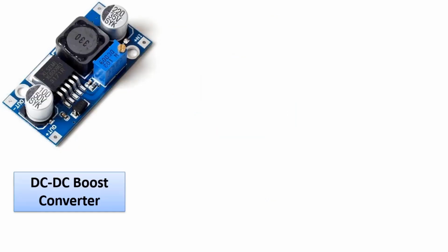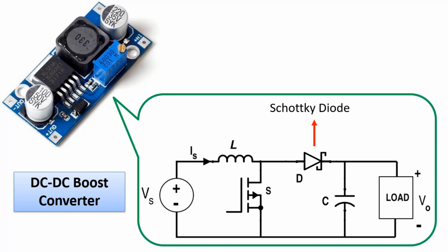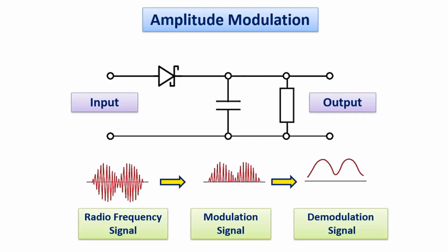Here you see a DC to DC boost converter. The circuit diagram is basically like this. The step-up process is based on the switching speed of the MOSFET in the circuit. In this circuit, triggers are made at high frequency values at the kilohertz level. Therefore, instead of using normal silicon diodes, Schottky diodes are preferred to respond to high-frequency switching speeds in order to obtain healthier results.